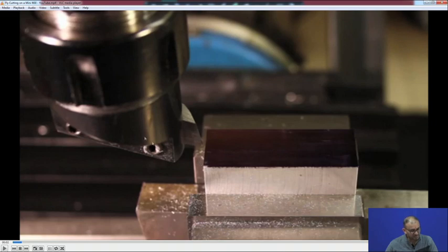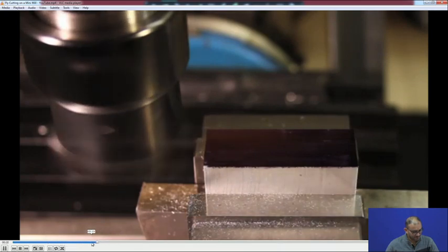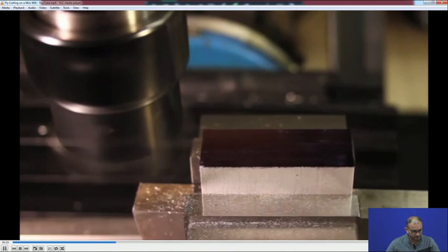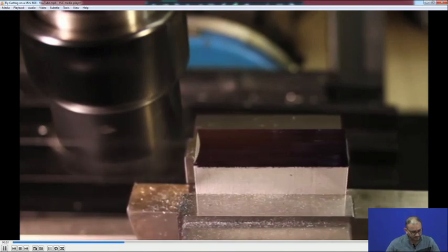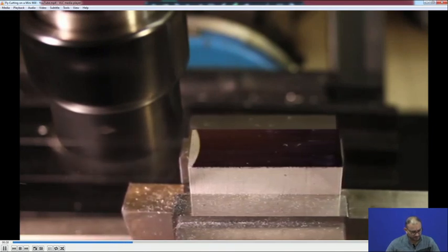To get this done, you have to rotate it at a high RPM and a very low feed rate, so you will not get any type of mark on the top surface. Now, you can see that it is rotating, and now you can give feed onto the workpiece. So, now it is removing the material.